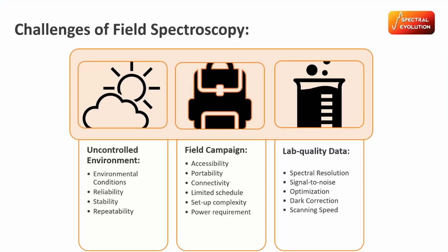It could be 30 averaging, which means it'll take 30 scans and average them together and give you one scan. And then after that, it will take another dark measurement, average the two dark measurements before and after, and subtract that off to get rid of any instrument noise. It's called a dark correction. By doing this, we're able to create some of the highest quality data in spectrometers and field spectroradiometers.